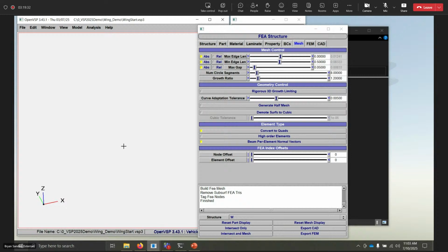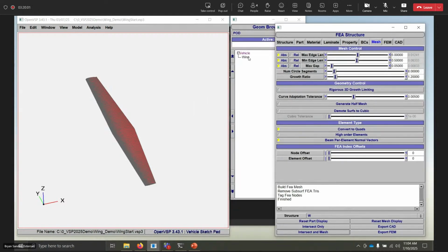What happened? Well, what happened is you were looking at your foot geometry, and you had set your wing, in my case, I'd set my wing aft of the nose and up a little bit. So my wing was 5 feet back and 3 feet up or something. And now it is 5 times 12 back and 3 times 12 up. So everything is moved out of your view. So the F button to refit back and forth between the two geometries is going to be really important. And I can demonstrate that.